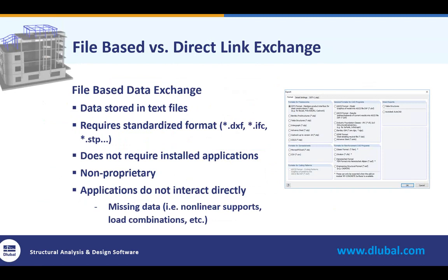So this does not require the installed applications. What this means is that both programs do not necessarily need to be installed on the same computer. Rather, we can take RFEM alone and create this data file and then import it into some other standalone program, whether that's on the same computer or a different computer. This is non-proprietary, meaning not any particular company owns this process, but rather this is a standard format for many standalone programs. We create these data files and then we can give them to colleagues or to other engineers to import or export into various programs.